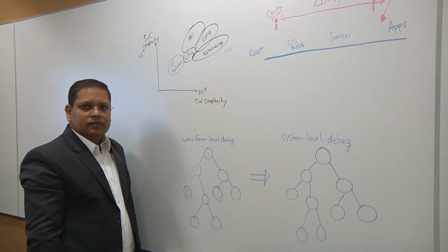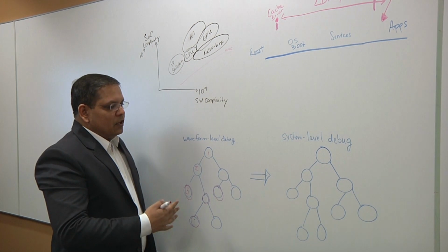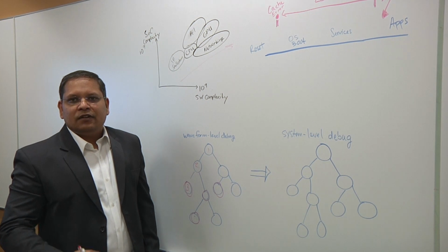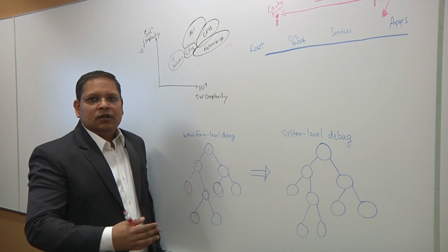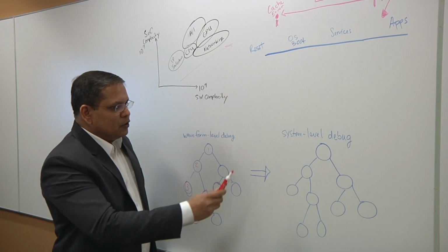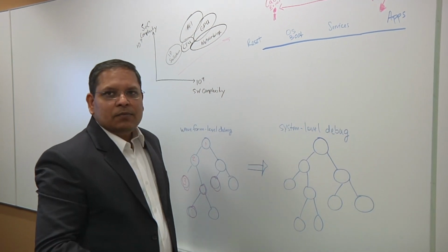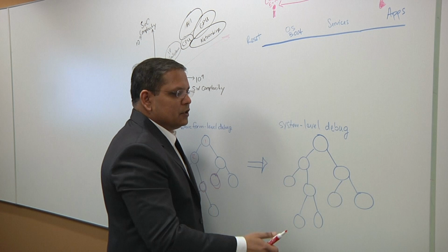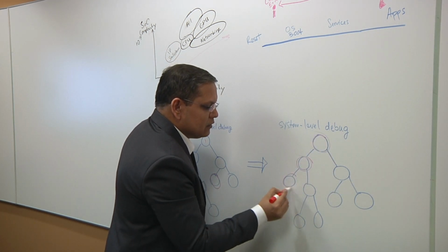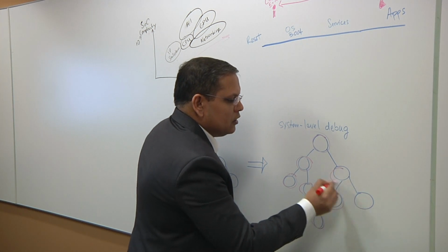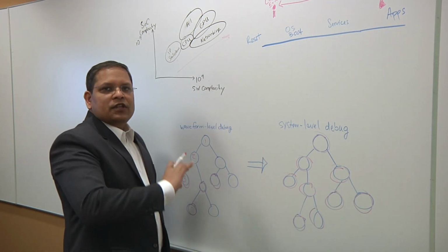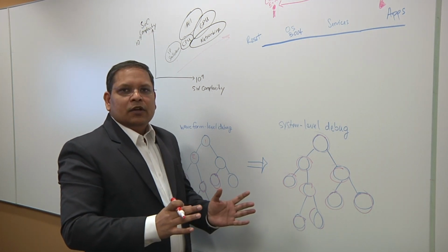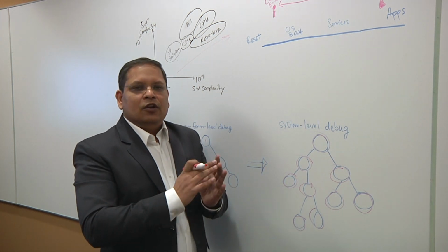So where are we now? What comes next? So now we need to figure out how we solve the problem. And what I want to do is stick with the graph theory, because that is really a nice algorithm to find a problem and define the search space. So I want to draw your attention to something that we call system level debug. And here the idea is that from depth first search, we move to breadth first search, and we are trying to analyze all the nodes in parallel. So the goal is that I want to see the entire graph, the entire design over the entire run, and try and narrow down the problem through some high level abstraction of the system.